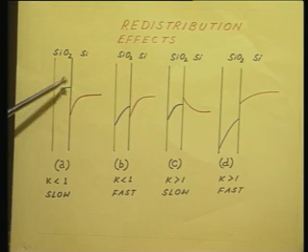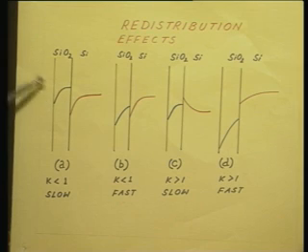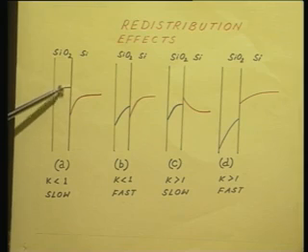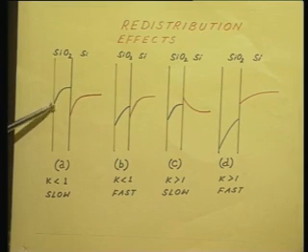And then it will remain more or less constant over quite a distance inside the oxide. That is because it is a slow diffuser in oxide. It cannot move very fast. Only towards the surface it starts to fall. Do you understand? This is when the segregation coefficient is less than 1 and the diffusion of the dopant through the oxide is slow.